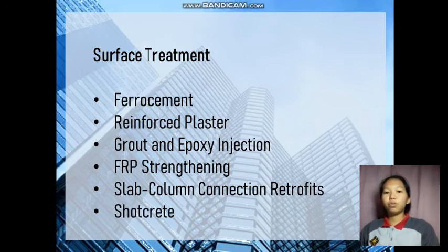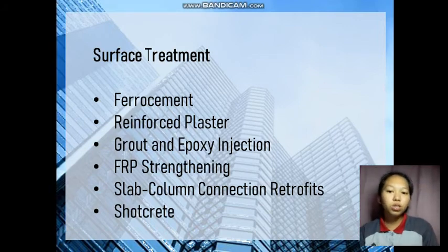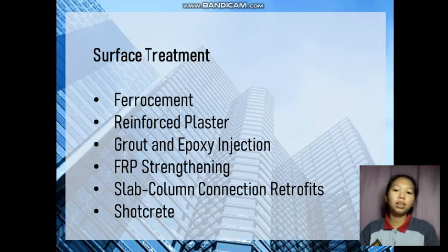In order to transfer shear across shotcrete masonry interface, shear dowels are fixed using epoxy or cement grout into holes drilled into the masonry wall. Retrofitting using shotcrete significantly increases the ultimate load of the retrofitted walls. This retrofitting technique dissipates high energy due to successive elongation and yield of reinforcement tension.